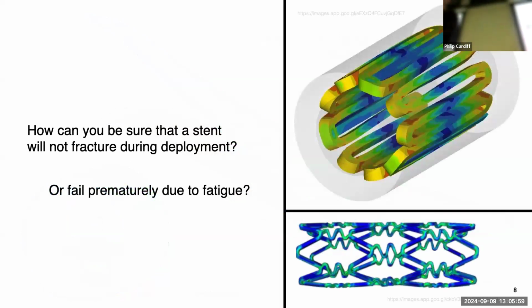Closer to home in Ireland, we have a lot of medical device companies. Many of you will have done internships at medical device companies. So, for example, for stents, many of which are made in Ireland, the manufacturers will perform stress analysis on them to check if they will behave how they want them to behave. So typically, once again, fatigue is important. They might look at the min and max strains, min and max stresses on their cycles if they're in vivo.